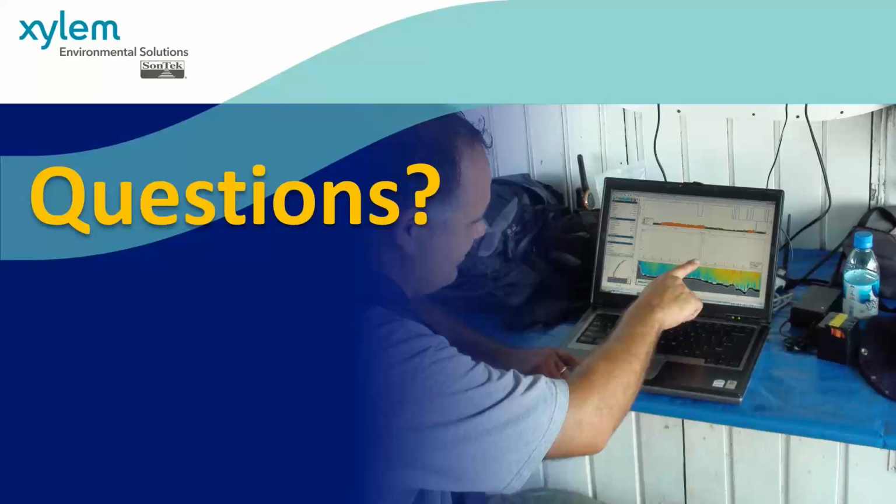But once you get into these more complex situations, especially during a flood event, then you might want to look at something else. Some of the choices are doing an index velocity rating for the site. Some people will look at the slope area method for discharge. Those are the things that we're actively investigating and researching. Yeah, that's a good question.